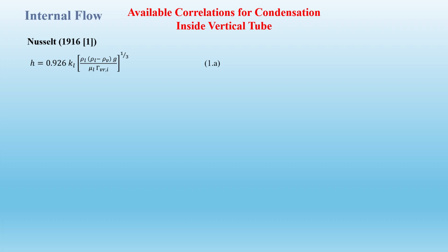And this equation, of course, has the same form or similar to those used in the condensation on outside of tubes. And this correlation depends on the condensate tube loading as defined in equation 1b, and it is applied for a vertical tube orientation.